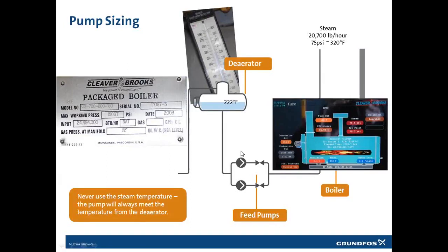The rules: the ASME code requires the boiler feed pump be able to put water in the boiler at the evaporation rate at a pressure which is 3% greater than the highest setting of the safety valve. That's simply a US design code, which we just meet. And normally we add 25% to the flow as catch-up. That sentence I have taken directly from Industrial Steam Incorporated, a large US-based company doing a very large amount of steam installations each year.